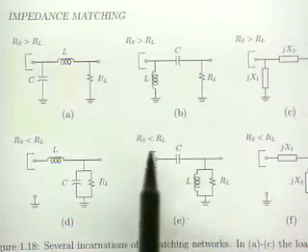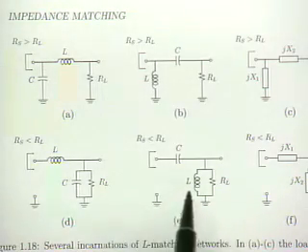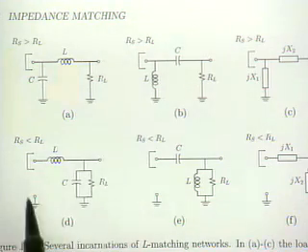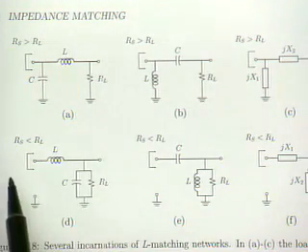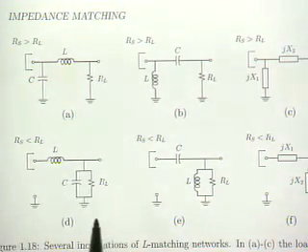So this is very convenient if I want to isolate the DC. The opposite is true if I actually want to preserve the DC. If I want the DC value of stage 1 to be the same as the DC value of stage 2, then an inductor is very convenient. So let me draw a couple of examples where you would use one or the other.